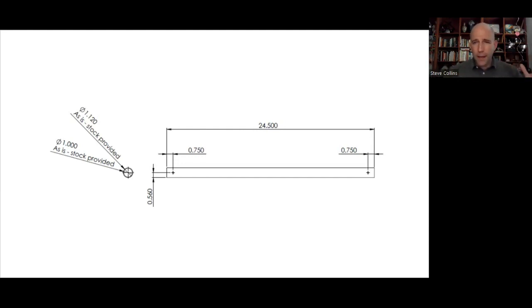So this is pretty big, a couple of feet long. It's very simple geometry, a plain tube, and it just has a couple of features in it, two holes that are drilled into either end. And this geometry is chosen to be simple like that on purpose because the intention is to use carbon fiber, where we can purchase the stock that has the right size, cut it to length, put a few very simple hole features in it, which is still kind of a pain. And then you get a nice stiff, lightweight, large, simple component.